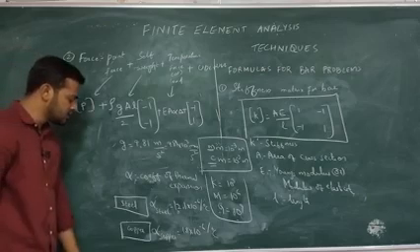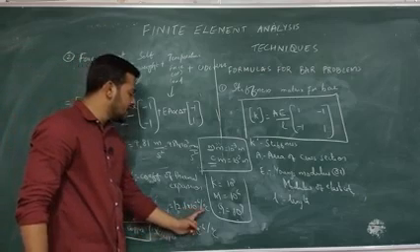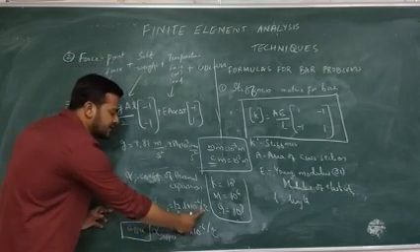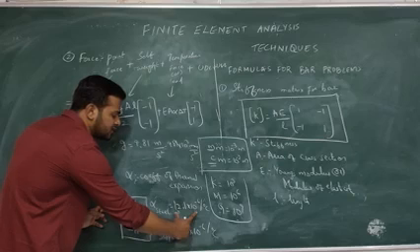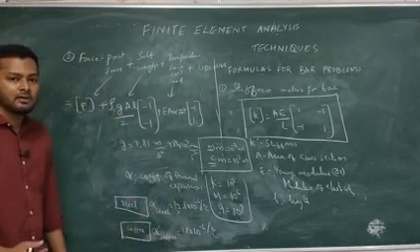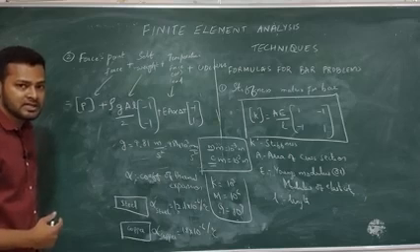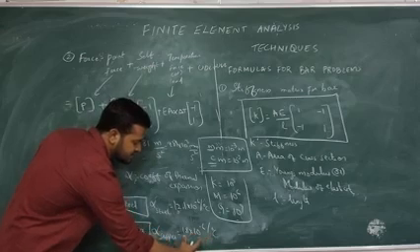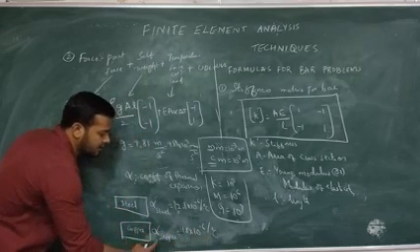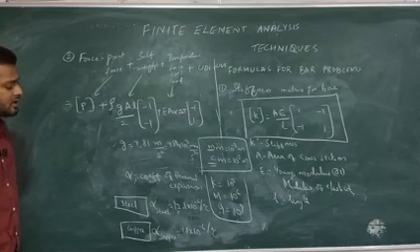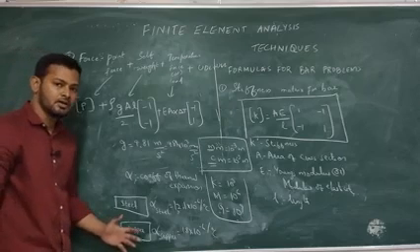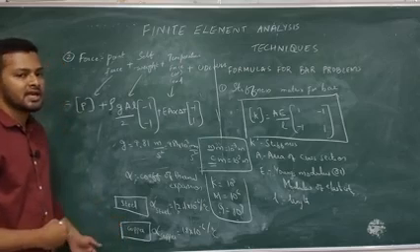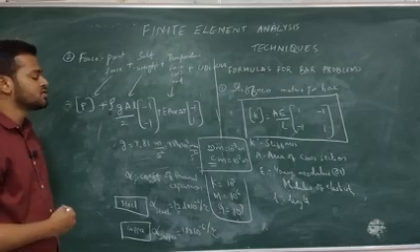So what will happen is, because of these values, if I am heating this member by 1 degree centigrade, the strain in this member will be 12.1 into 10 power minus 6. That will be the strain in this member. If I am heating copper by 1 degree centigrade, the strain in copper will be 18 into 10 power minus 6. What is strain? Strain is the change in dimension compared to its original dimension: change in length by original length, or change in diameter by original diameter.